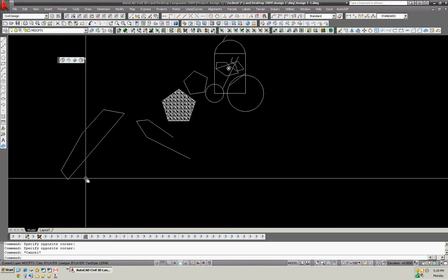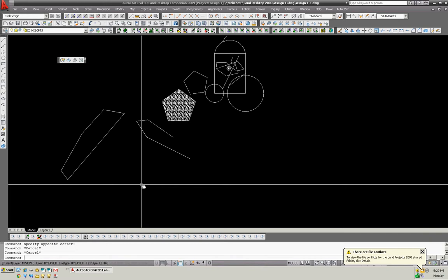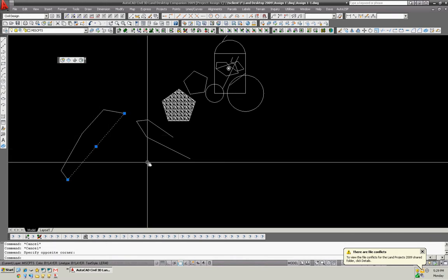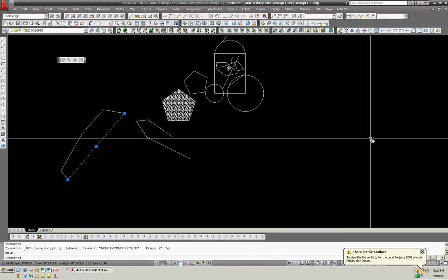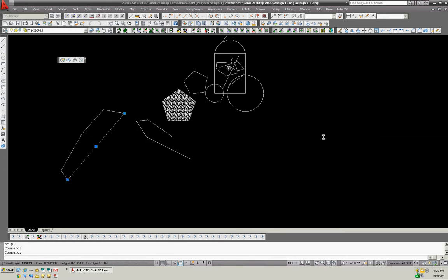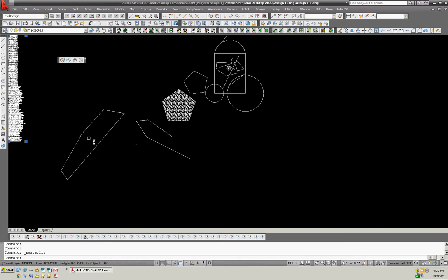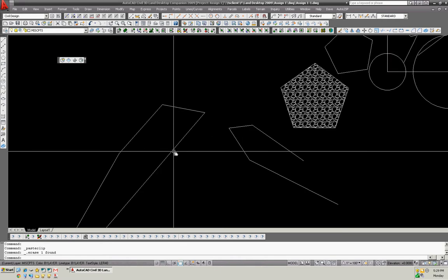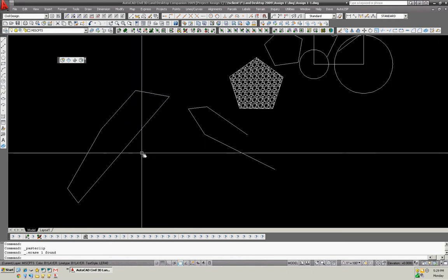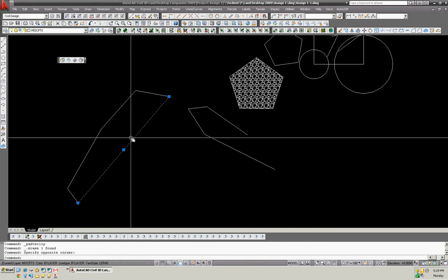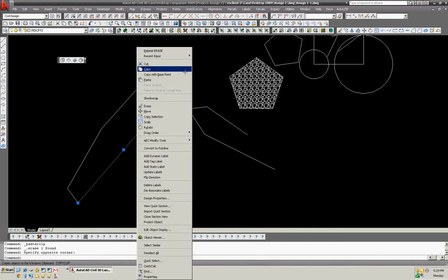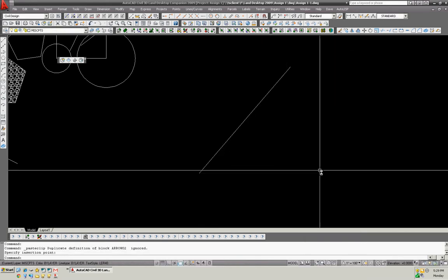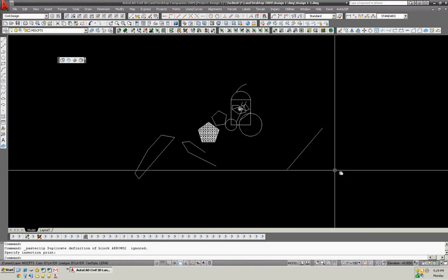The last command that I'd like to teach in this video is copy. There's copy and paste, and a couple different ways to do this. You can select something and type in Control-C like you're used to, and then Control-V, and it'll copy something for you. I had something on my clipboard from previously. The best way is to select a line, right-click, and hit copy, and then right-click and hit paste. And you can paste a line or any other feature that you'd like.